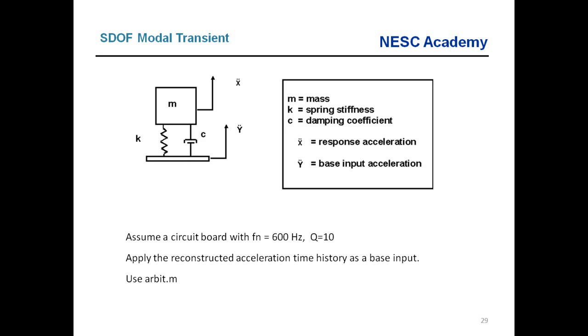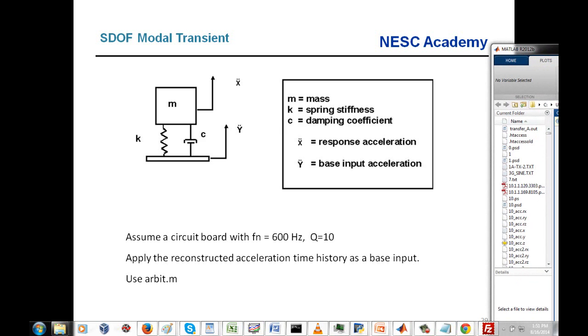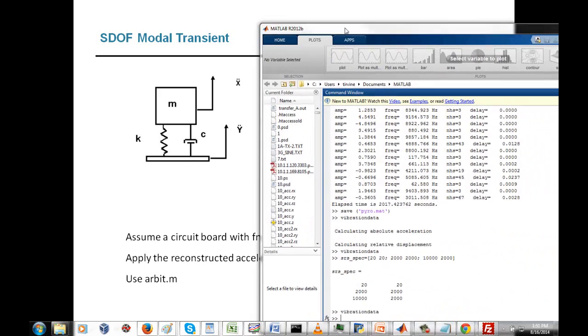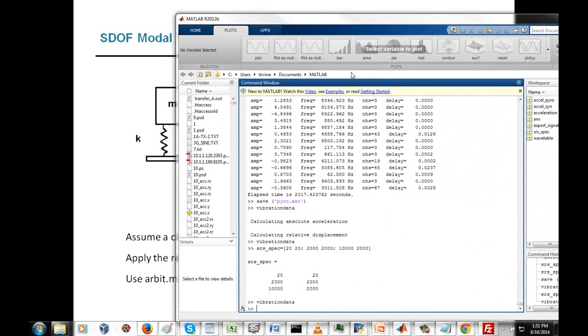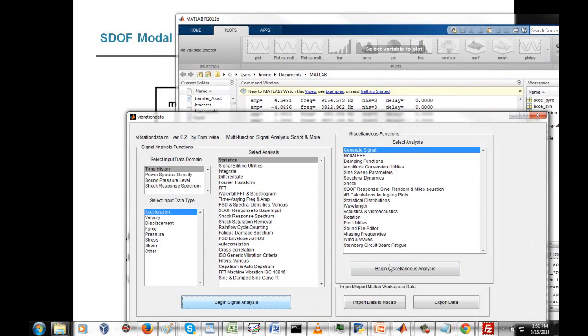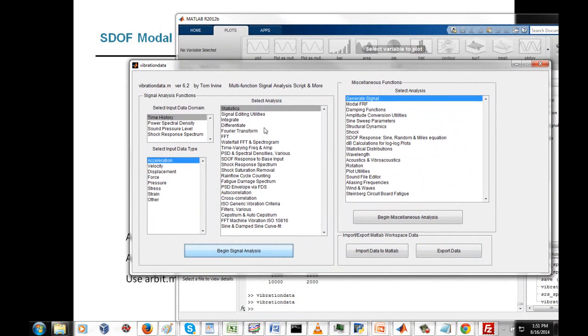And by now you should know the routine with free body diagrams and Newton's laws and second order governing equation of motion and all that, and convolution integrals, and David O. Smallwood ramp invariant digital recursive filtering relationship. Let's see what happens at 600 hertz, Q is equal to 10. So we have our time history here, and we have single degree of freedom response to base input.